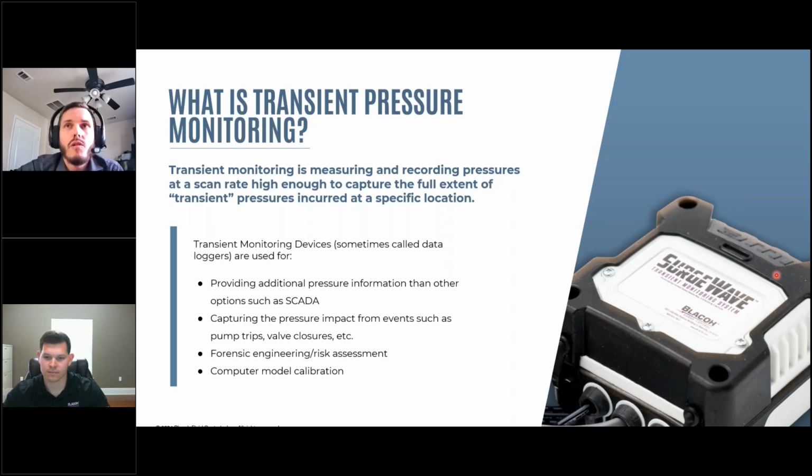Now, armed with the whole pressure timeline, you're able to do root cause analysis if there's a failure, whether minor or catastrophic. For example, triangulation can be used to determine where the wave was originated from. Once the culprit is identified, then mitigation methods can be accurately proposed instead of just coming up with a band aid solution. Like, did that pipe main from the 50s break due to water hammer? Now we can tell if water hammer was a contributing factor besides just blaming the failure completely on rust and corrosion.